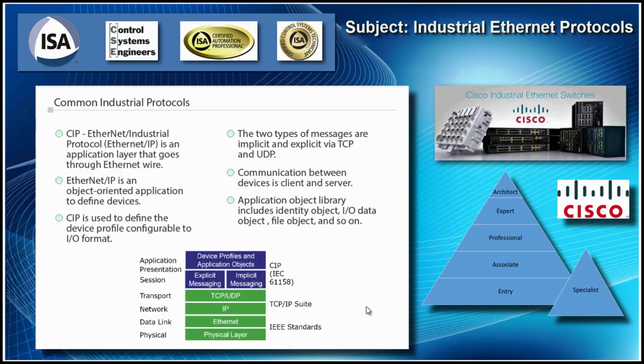Additional architectures and protocols used in the industrial environment include data exchange protocol models such as Common Industrial Protocol, or CIP suite. CIP is an information exchange protocol for industrial automation applications. CIP allows users to integrate manufacturing applications with enterprise-level Ethernet networks and the Internet. CIP is a messaging protocol that defines how different industrial automation and control system network devices, systems and applications come together to form an application.